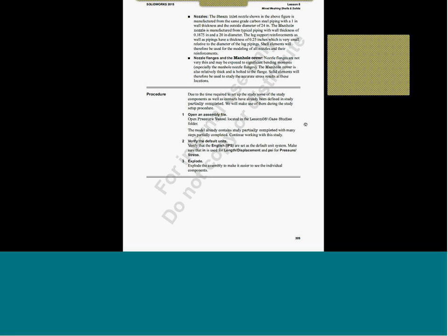So frankly, from a process perspective or a theory perspective, the only difference or the important thing that we need to understand is this one. That is, when we are mixing solids and shells, we are not transferring the rotational degree of freedom. Whereas mixing shell and beam is fine, both have 6 degrees of freedom. Mixing beam and solid can again create a complication. It's not a huge complication. It has its own means of handling it. It is enough if we know and manipulate the things appropriately.